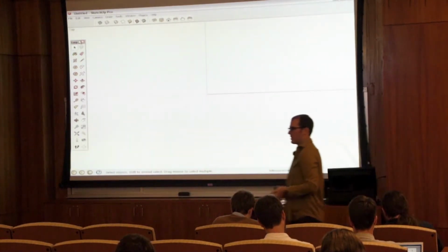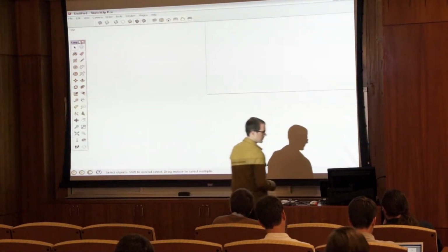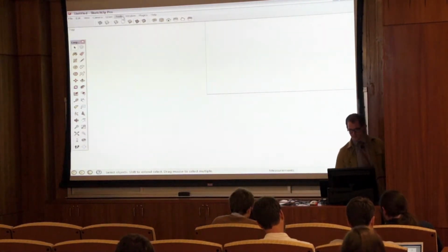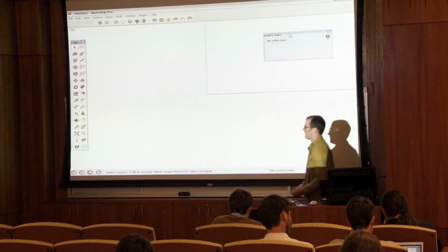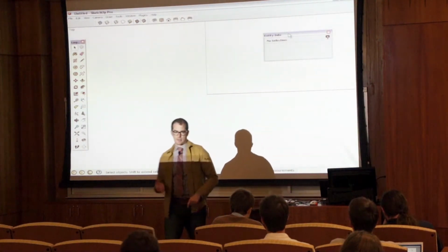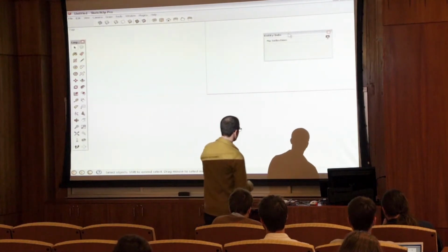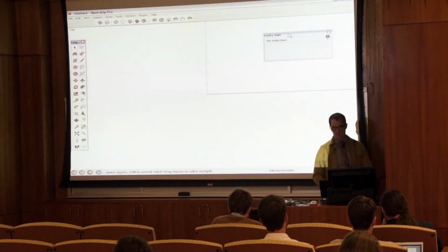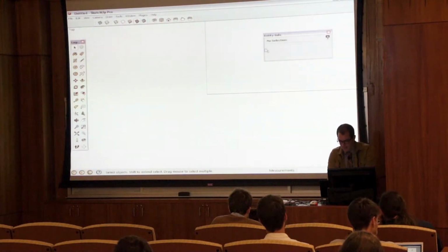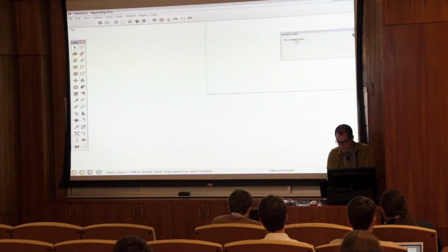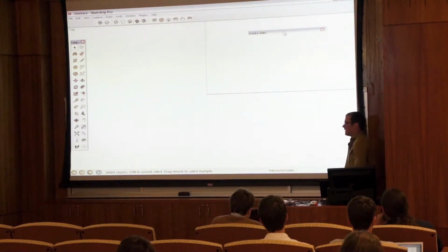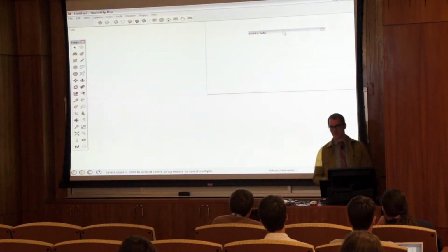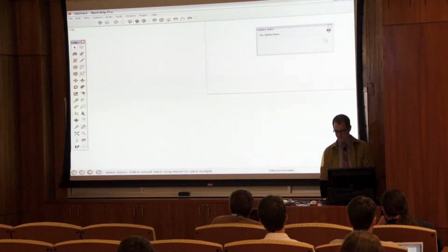And then you'll eventually have window palettes. You'll see those as we work through, but basically anything under Window, like entity info, these are tool palettes. You'll get the paint bucket, shadow settings, there's a ton of them. But these tend to really take up a lot of real estate on your computer. So a nice little feature of these, you can just click on the name, sort of the area at the top, and that's going to dock it for you. Another great solution is if you have dual monitors, dock all your tools on one side.